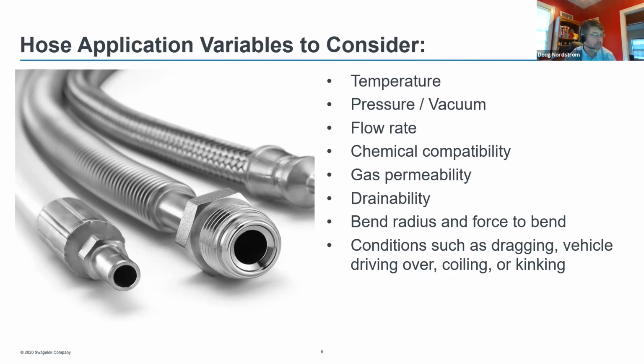Again, many times a hose is used as a bit of an afterthought. We've seen hoses used as a handle to pull doors open and close. That's going to cause a lot of damage on a hose. It needs to make sure that we see what it's going to be rubbing against, abrasion issues and potential kink points, so that we know how durable and how robust the hose needs to be when we decide which one's right for that application.